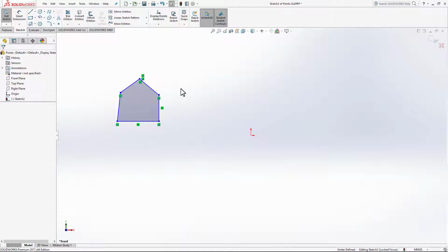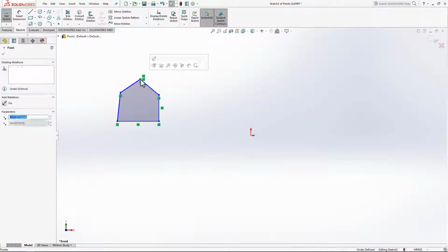We can apply relations between sketch entities. This is different from giving them dimensions. We'll get to dimensioning the sketches, but for now, I want to show you what these green symbols are. There are a few of them. This type here is called coincident, which means that two entities are attached together. In this case, the points we created, which are shown with asterisks, with the endpoints of the line. That is why when you drag the points, the lines go with them and vice versa.